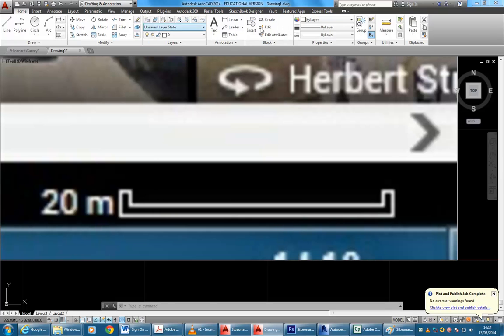Alright, so with the distance tool, I'm going to measure from the centre of the line. Now, this might seem like a little thing. I've written a massive essay on this, and I know an architect who did basically his whole thesis on this, where to measure on the line. And so anyhow, just to get you thinking about that, in this case, the centre to the centre is where you should measure. So from the centre here to the centre on the other end, not from the inside there to the inside or anything like that. And any little errors here are going to be magnified, so you want to be as accurate as you can.